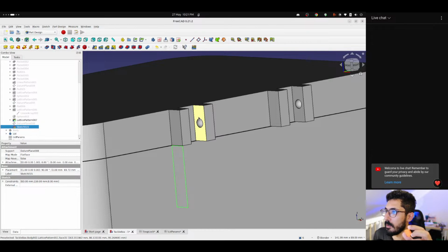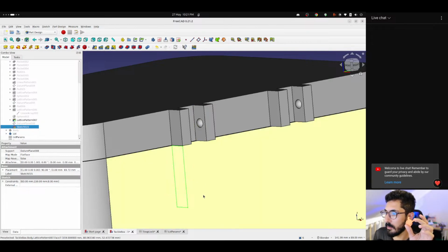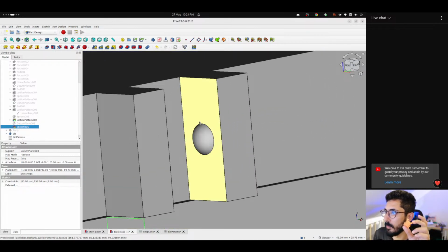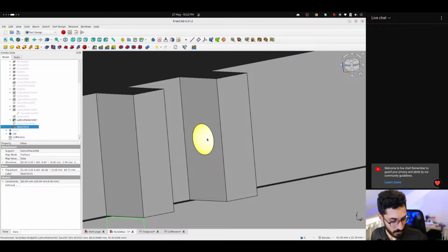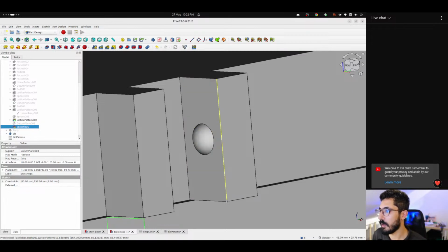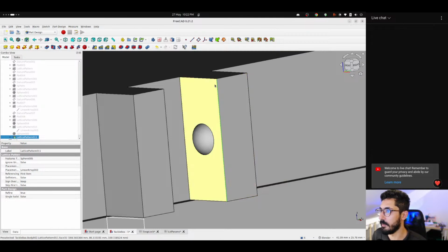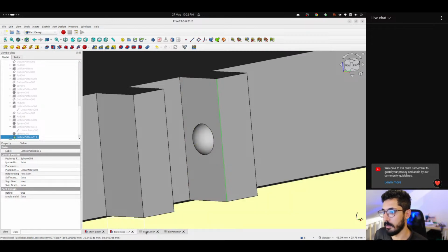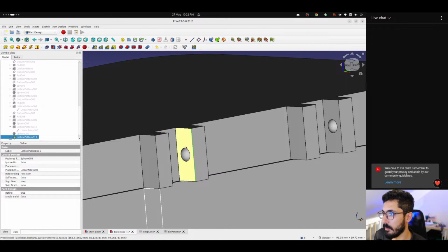So this is where the snap starts. And then it's gonna end somewhere here. So we need the distance from here. So the ball is at the center, and we have this total height. So if we divide the total height by 2, we're gonna get the center. And then if we go up by radius, and then we can go up by 1, we will have the distance from basically the top of this to this line right here.